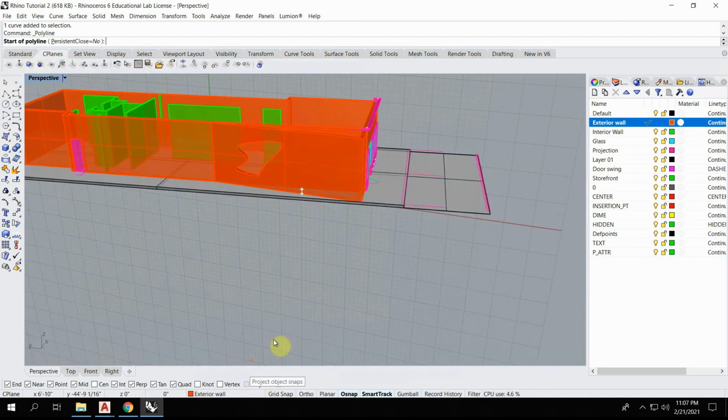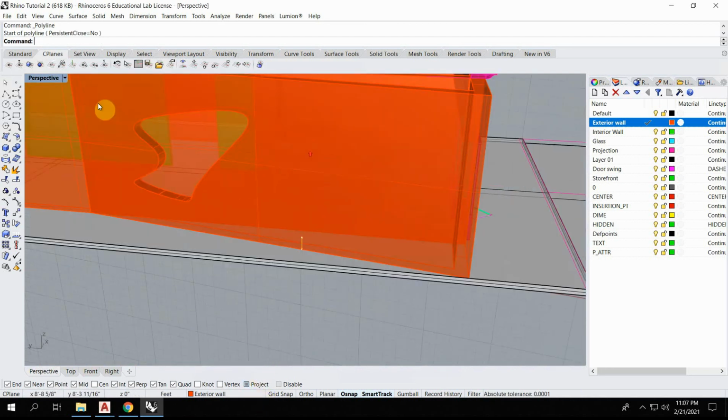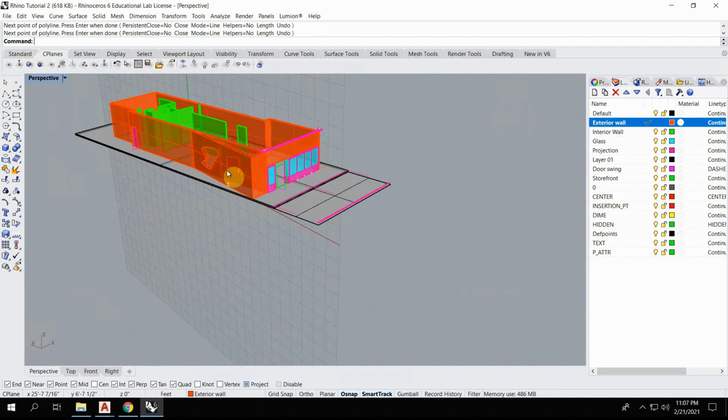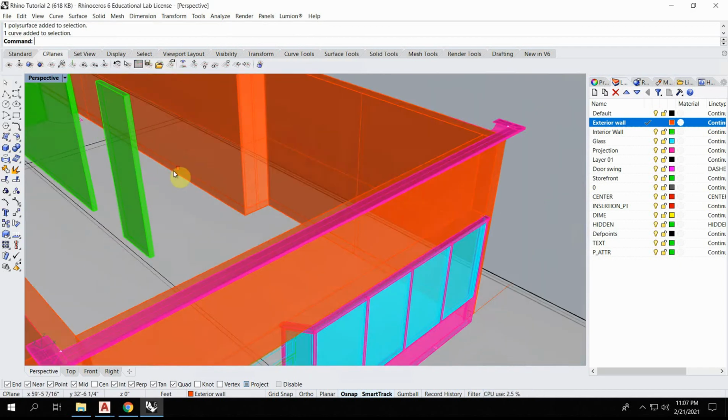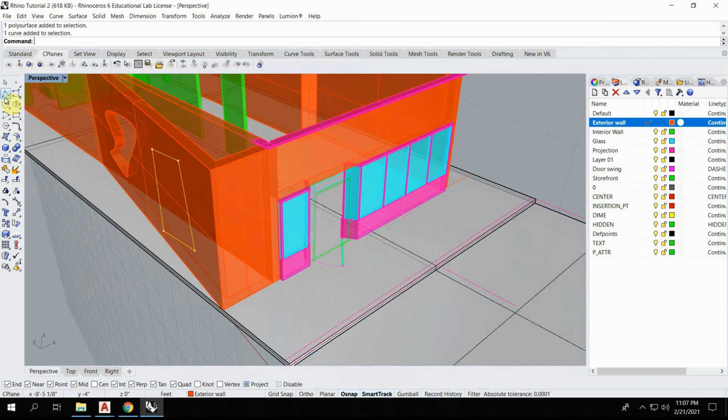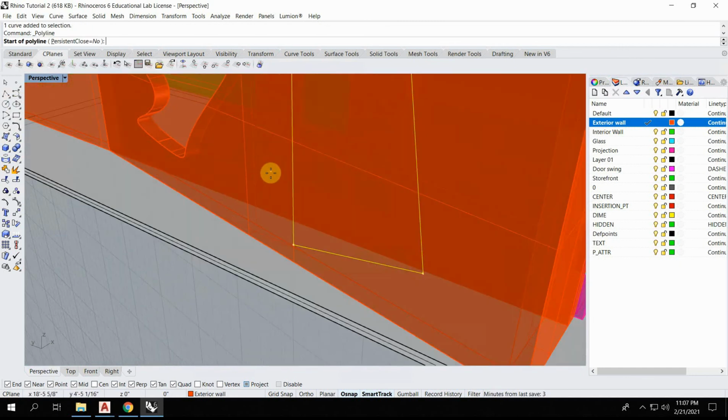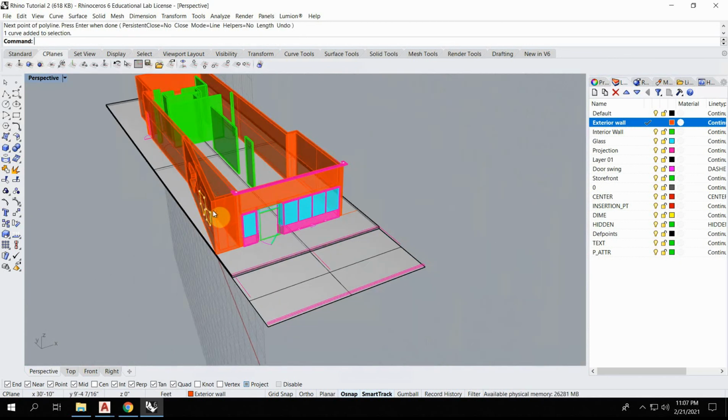So now if I hit project and I'm drawing on here, it should be drawing like it's actually on here, because it should all be in that plane because I defined that plane. So let's try that again. Normally if I do project, it'll put it all at the 0, but this should all be on that plane, which is great.